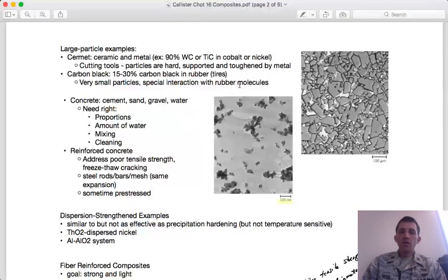But if you have all of these tiny particles in a metal matrix, then you don't have the same problem with brittle fracture because they're basically already in teeny tiny pieces. And if they continue to break further while you have other particles nearby, you're not going to have a crack propagate through the entire material. In fact, a crack has to go from particle to particle through the metal matrix, which allows metals to deform and gives it some fracture toughness. So here you see an example of how you get the really high hardness of these carbide particles, but with the fracture toughness, say, of a metal, to make a very hard, long-lasting cutting tool.